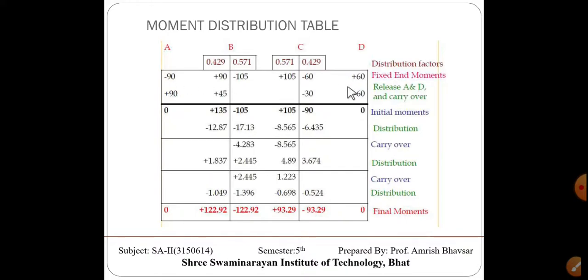And dear students, the most important thing we have to remember over here is that whenever our end supports are simple, then we have to take 0 moment over here. So how can we get 0? It is 90, then take plus 90, so it is 0. Here it is plus 60, then take minus 60, it is 0. But whenever we do this moment, we take half of this moment over here, and here also half of the moment is taken at C.